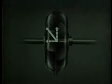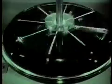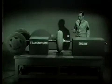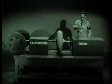This dual motion of the oil combines to send it in this direction. Increasing the velocity of these flows eventually transmits the torque, or turning power, from the engine through the fluid coupling's pump via the turbine to the drive wheels. When used in place of a conventional clutch, the fluid coupling is an effective liquid link between the engine and the drive wheels.